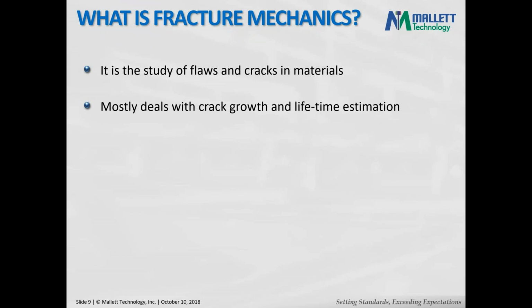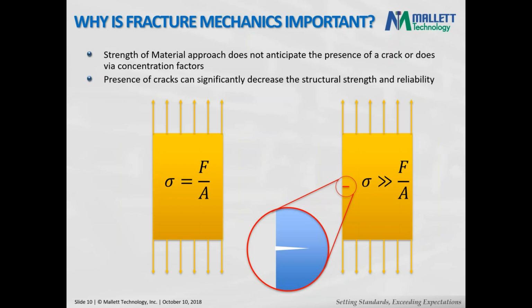What is fracture mechanics? As most of you know, it's the study of flaws and cracks in materials. It mostly deals with crack growth and life estimation. Why do we study fracture mechanics? Because the strength of materials approach cannot really calculate what happens to the stress state when we have a crack. The presence of cracks can significantly decrease the structural strength.